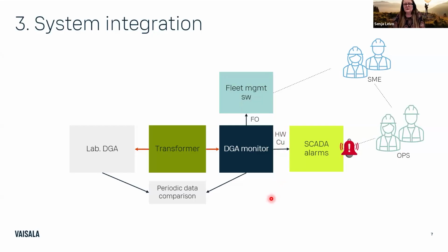It's based on one of our customers' setups. The transformer is here, and the monitor is taking oil every hour or so. They also continue having a lab DGA, so they still take samples, though not as frequently as they used to. This is a GSU again, and from time to time they compare the lab and the monitor reading.